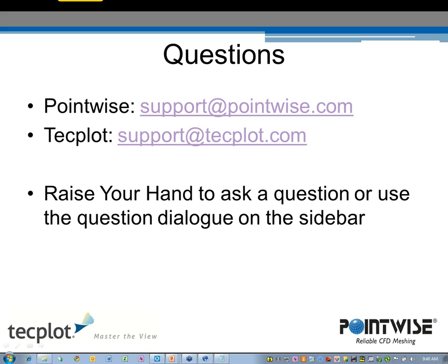Okay. Chris, this is perhaps for you: how can you be sure that the solution is mesh independent using the optimization method? Well, like we showed on the chart, Travis performed a mesh independence study. I think the finest mesh I showed earlier in the presentation was 100,000, but he went up to 500,000 in 2D, and there was no change.